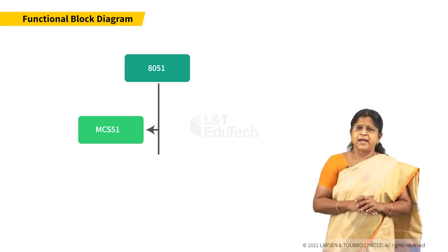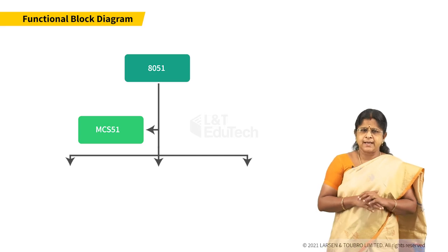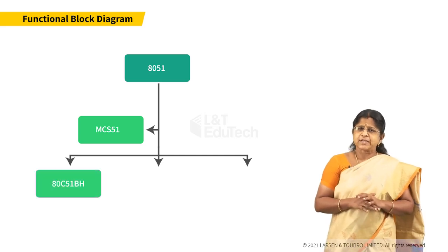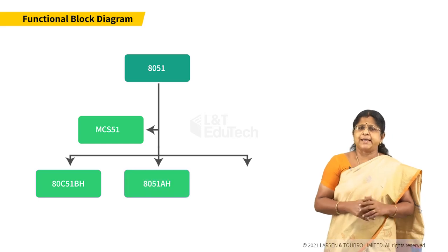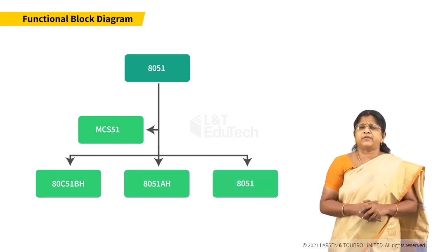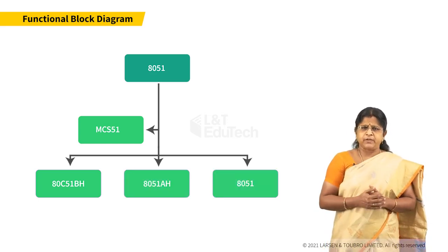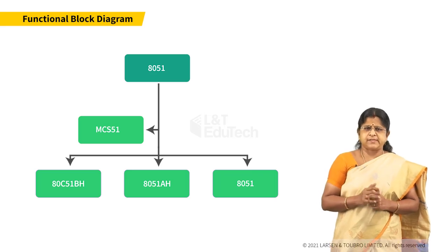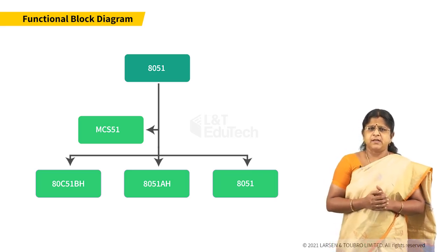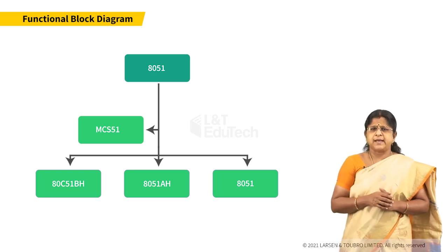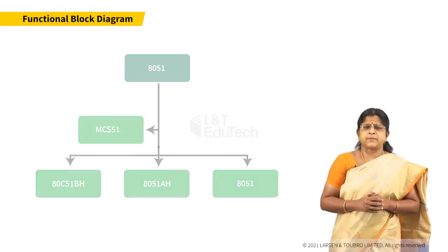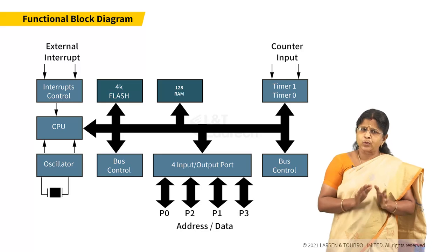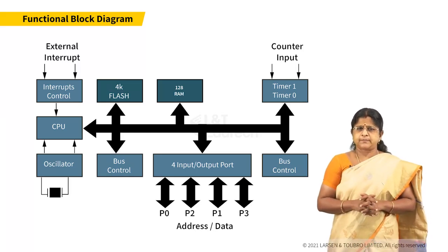8051 itself has its own family members as 80C51BH, 8051AH and 8051. Each one of them will have minor differences in probably number of pins, the ROM's presence and the number of timers. Our discussion will be more generic and we will explore the major blocks.